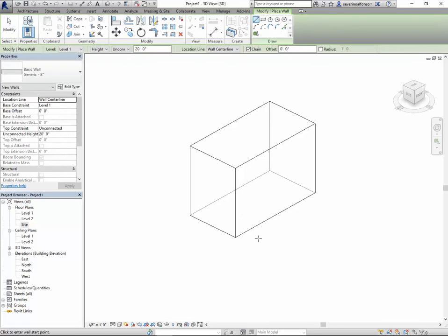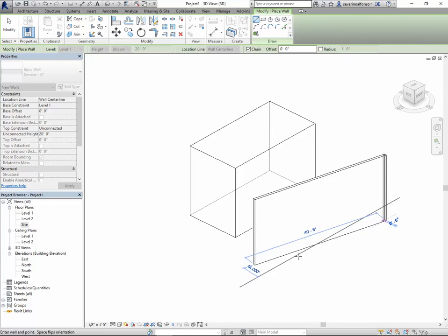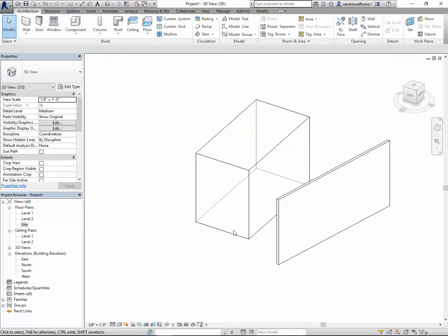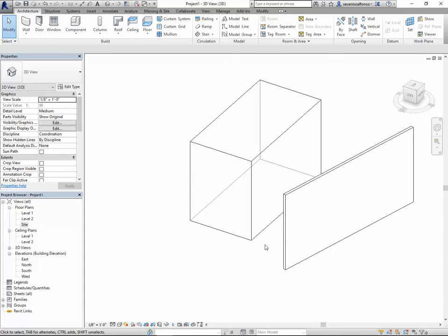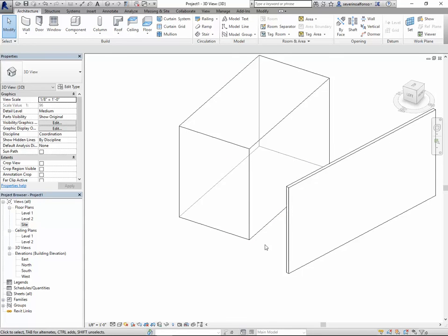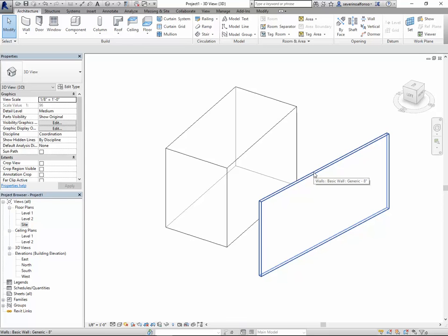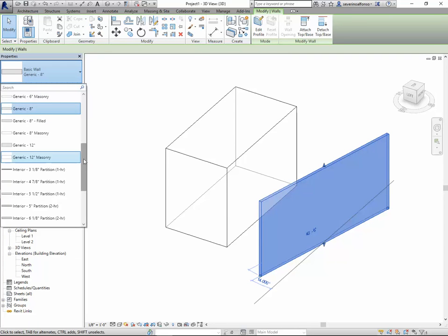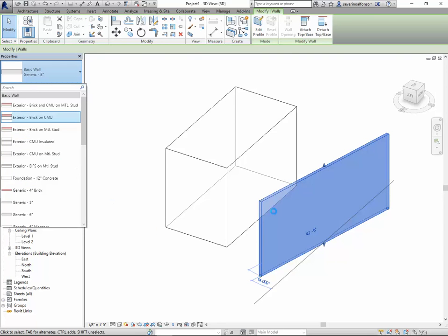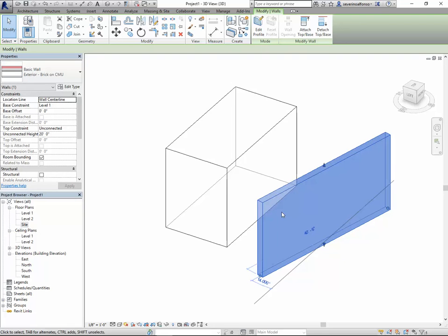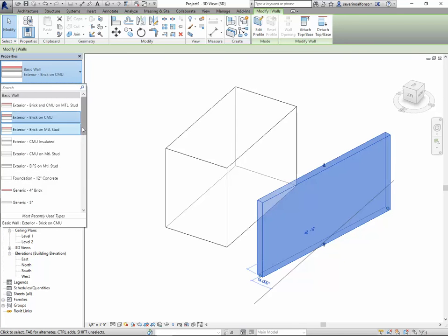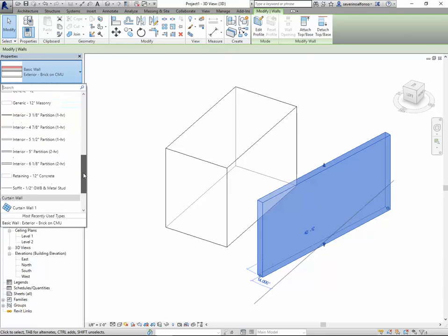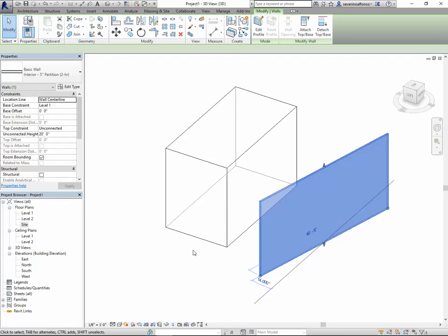If I click on walls and drywall here, this will be a wall. They look similar in geometry, but they're entirely different kinds of geometrical entities. This is project material, let's say project entities, that you've selected, and you will see a different set of parameters, such as wall parameters. You can change the type of floor, and it will change automatically. As you can see, it gets thicker in exterior walls, or you can do interior partitions, a little thinner.